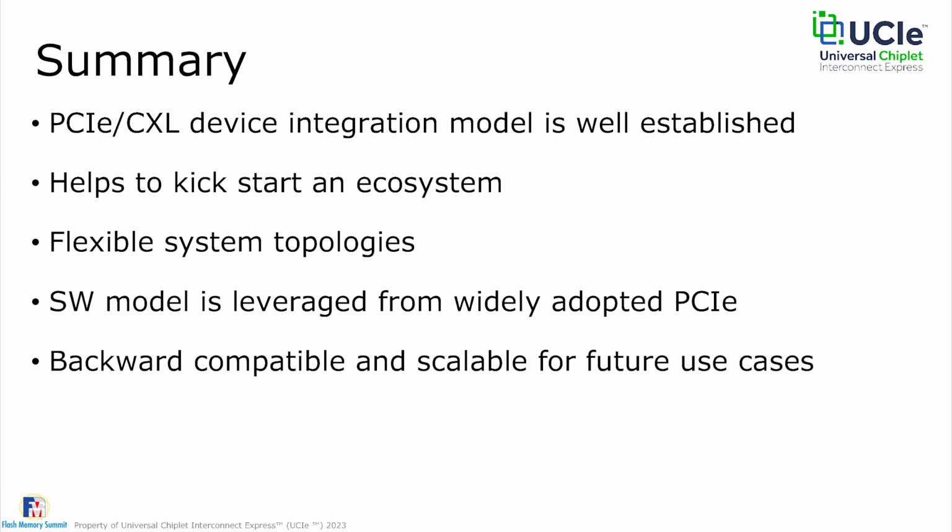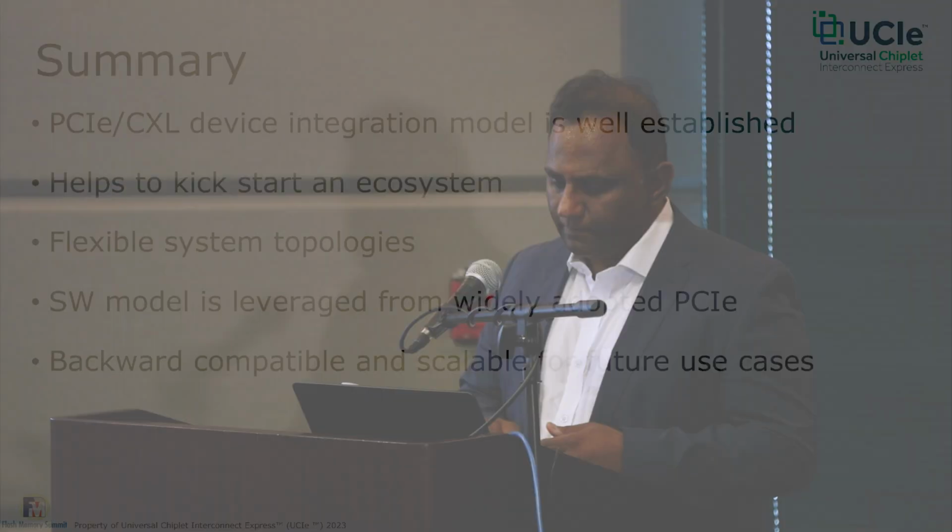A lot of the examples you already saw, right? It can be a tree topology. It can be a star topology. It can have all kinds of IP integrated, chiplets integrated. All of that is feasible with the existing UCIe, right? And it's a mix of standard protocols and streaming protocols. The software model, as we discussed, is leveraged from widely adopted PCIe. And of course, it's backward compatible and scalable for future use cases. All right, I'm going to pause here for just a minute to see if folks have questions, and then we'll jump into the manageability section.